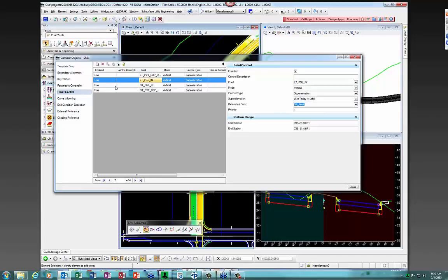And then the same thing on the outside. So these are being controlled. These are basically being created behind the scenes. Once you understand how all this works, then applying superelevation on projects gets really, really simple. Because now I have a specific line, and let's say I had another 4-foot lane out here that I forgot to put superelevation control on. All I've got to do is assign the same control line that controls this point to this outside point, and now I'm controlling that outside point in the same way as this, which is what you typically want to do anyway, unless it's a different slope.